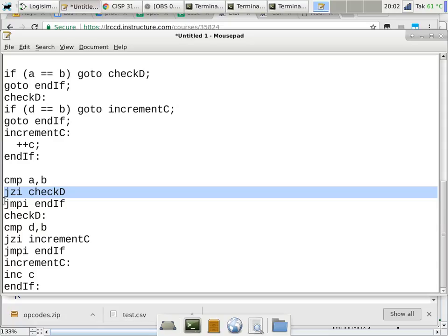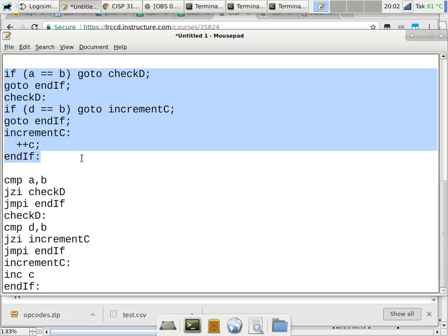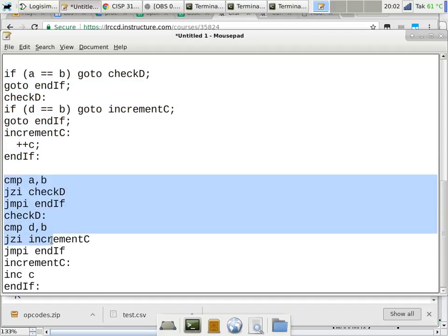So this is the very last step that you can still test using a C compiler and a C debugging environment. But that takes you a long way, because from here to here is a very, very mechanical process. If you name your labels right to begin with, this conversion process does not involve any new labels. You're only breaking a comparison operator in C into a compare followed by a conditional branch.